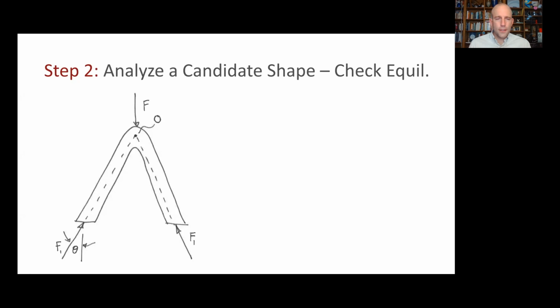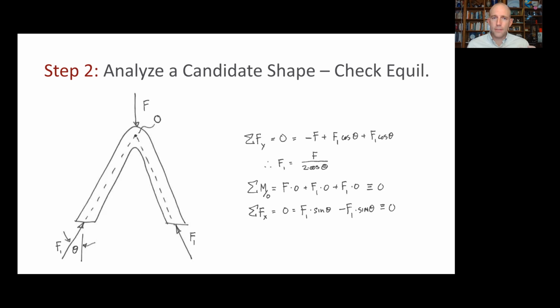All right, so hopefully, once you've made some assumptions about the forces, the equilibrium equations aren't too bad. They're pretty straightforward. And we'll see that, yes, it is possible. So if we look at the sum of the forces in the y direction, we're going to see that they need to be 0 or this thing would accelerate. And we have a force downwards of F, negative F, and then 2 y components of our 2 foot forces, F1 cosine theta plus F1 cosine theta. And here, notice that we've had to define a geometric parameter in order for this stuff to make sense, and we're going to collect those as we go through our analysis. So we're saying that the angle from vertical of the legs is theta.